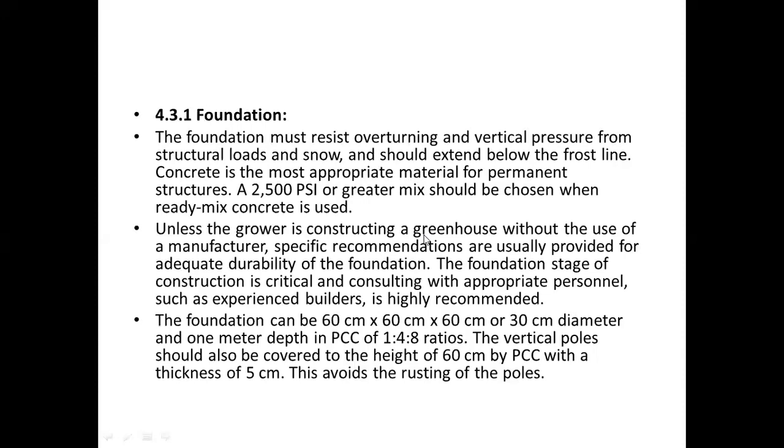So, the foundation of the greenhouse they have mentioned. They have told about the foundation mix, and what the dimensions for the foundation must be. They have told us that a 60 centimeter cube must be the foundation for the greenhouse structure, and a 30 centimeter diameter foundation for the poles should be used, or 1 meter depth of PCC.